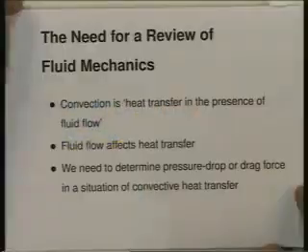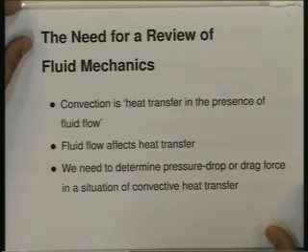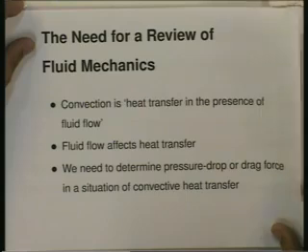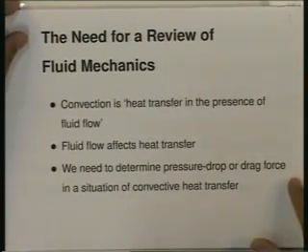Also, in any heat transfer situation, if there is a fluid flow, we will have to determine the pressure drop of the fluid as it flows through a duct or a passage, or the drag on a surface or an immersed body, if that body is immersed in a fluid and is losing or gaining heat from the fluid.